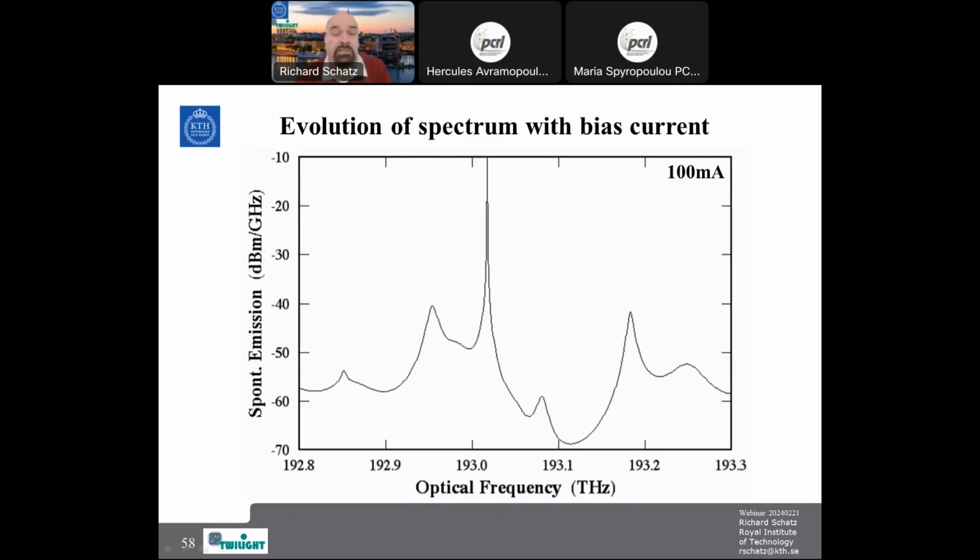Now they go into each other, and in this laser, we in fact get self-pulsations if we increase the bias further. So then you get mode locking between the main mode and side mode in this case. But just before you get mode locking, you get very large bandwidth here. So you resonantly amplify your modulation response at these frequencies.